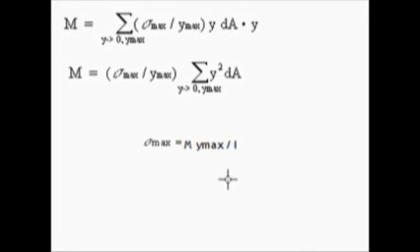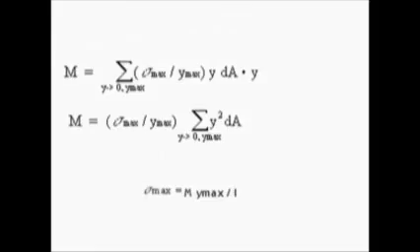So that is your maximum bending stress at one location. Since the formula is derived for the maximum stress, it actually holds for the stress at any point in the beam cross-section, and it is now known as the flexure formula.